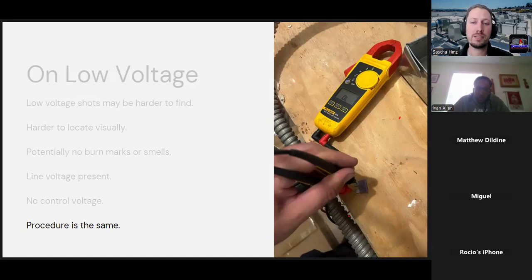We then obviously turned off the power. We usually do that, turn off power. Then we took our meter, we put it on resistance. We checked terminal to common. So we would go R to C. We would check what our resistance was. It was good. Then we checked our W1, G, Y1. We check all of them to common. In this specific scenario, we had on Y1 to common, we were reading 1.5 ohms, which is very low. The only thing that you would be reading on that is probably your contactor.